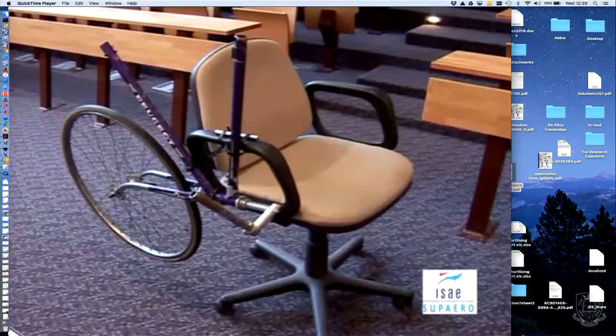If you put the gyroscope inside a gimbal, okay, a gimbal is like a frame that holds it. What happens is, you attach the gimbal to the aircraft, and as the aircraft and the gimbal move, the gyroscope tries to stay in the same place, okay? And so they were used a lot for giving pilots horizon coordinates, okay? So wherever the aircraft was moving, the gyroscope would stay essentially on a horizontal horizon if you set it up that way. And so that's a traditional way that they've been used in aerospace engineering.